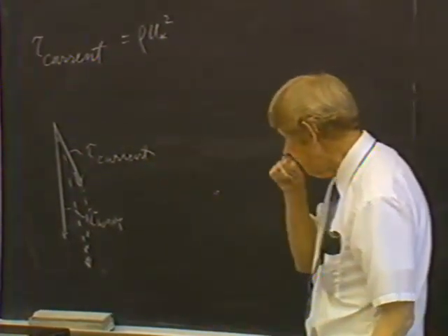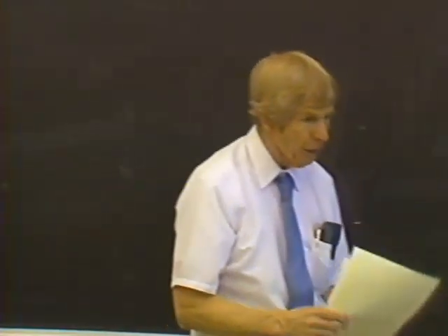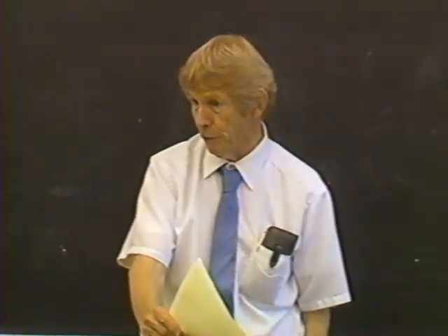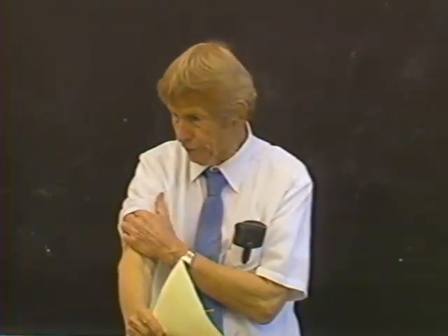However, in most circumstances, in shallow bays anyway, the current stresses are so small compared to the waves that you normally just neglect them. You just consider the wave.